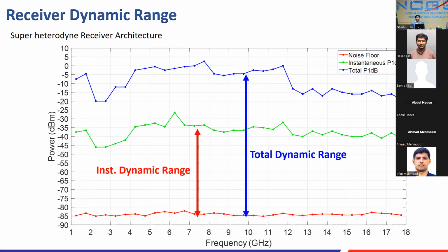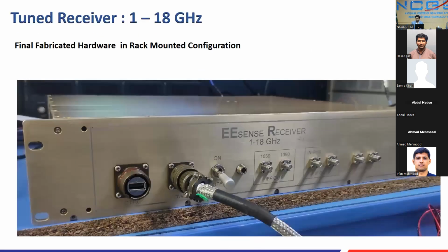That is for a single carrier. When you measure it with two carriers at the same time but at different power, they do intermix. Then you have SFDR, spurious-free dynamic range, at this much power. That is also a parameter you may consider for receivers. So that is the first, the improved version.